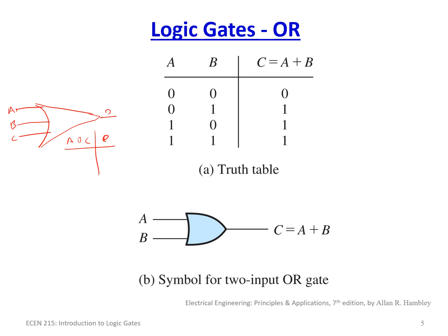D is the output, and there would be, again, 2 to the 3, 8 rows. And of course, the first one is 0, which would be a 0. And then from here, 0, 0, 1 would be a 1, or 1, 1, 1, and it's all ones all the time. The only time that it is a 0 is when, in this case, A and B are both 0. Which, by the way, De Morgan's law works with this. So if you wanted the inverse logic of F, this would become the AND gate in an inverse logic. So that's just a side note there.